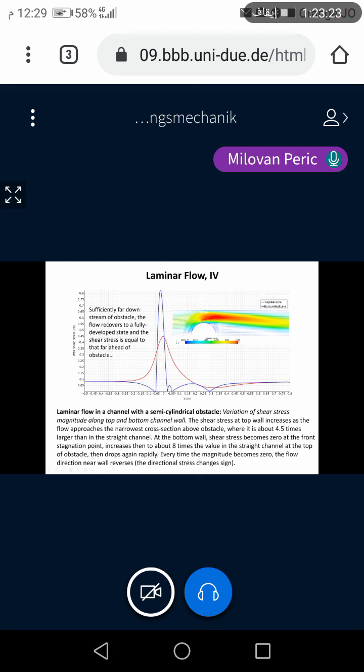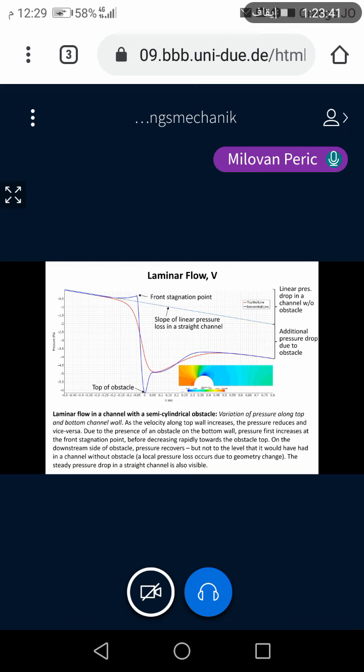And the zero before it is because there are two recirculations here in opposite directions. But as I said, because of weak flow, they are not visible. So you see that now the flow pattern near the bottom wall and top wall are totally different because of the difference in geometry. If you look at pressure variation, it's now different to inviscid flow.